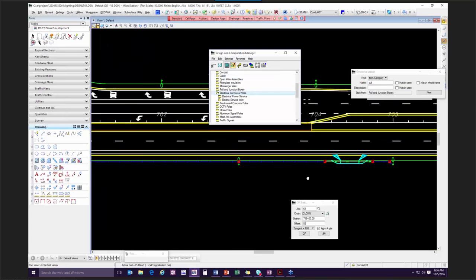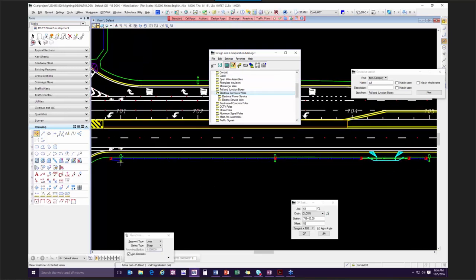In this scenario, we'll just use these 3 poles right here. You'll have your conductors coming to this pole box from wherever your power source is, and say these 3 poles are all on a circuit. The way that this needs to be calculated is per conductor for the length of the conductor. So I can't necessarily use the conduit. So I've got 1, 2, 3 poles. These 3 poles each, so when it gets to the pole box, there's going to be 3 lines that are going to come out for this particular one. So I've got 3, 6, 9.